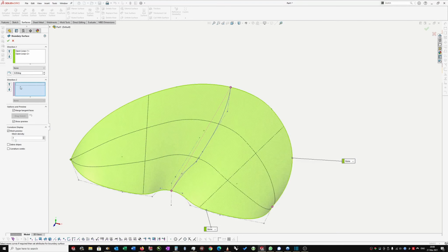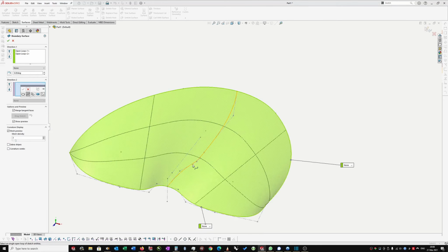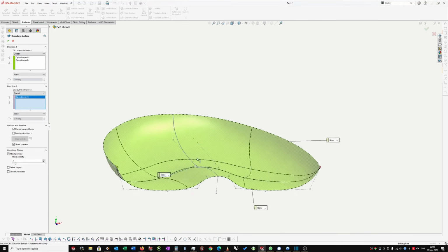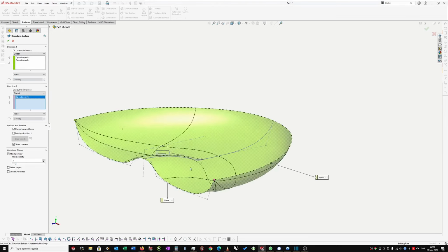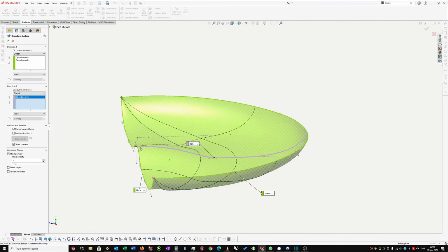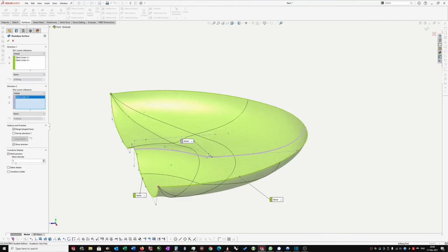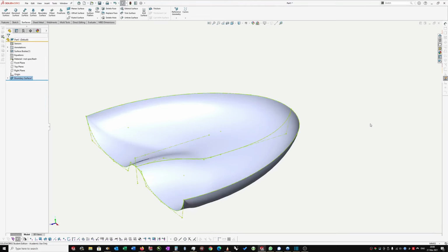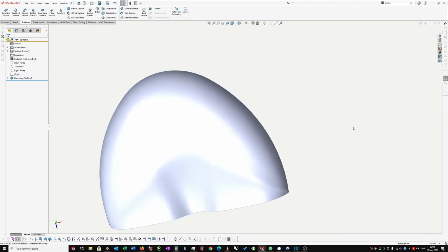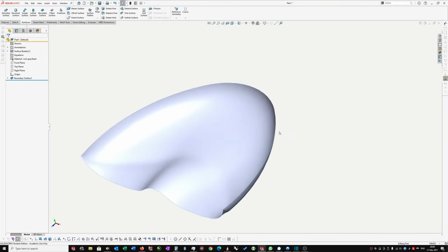And you can see it's actually given me a pretty decent, equally sided surface. But it does help to go in here and say Selection Manager and select this one. Say OK, because now that's just kind of flattened the floor and given this interior much more definition. It's also tapered this mound off so that you're sort of straddling it when you sit in it. Alright, so once you're happy with that, you're done and you've got your primary surface.